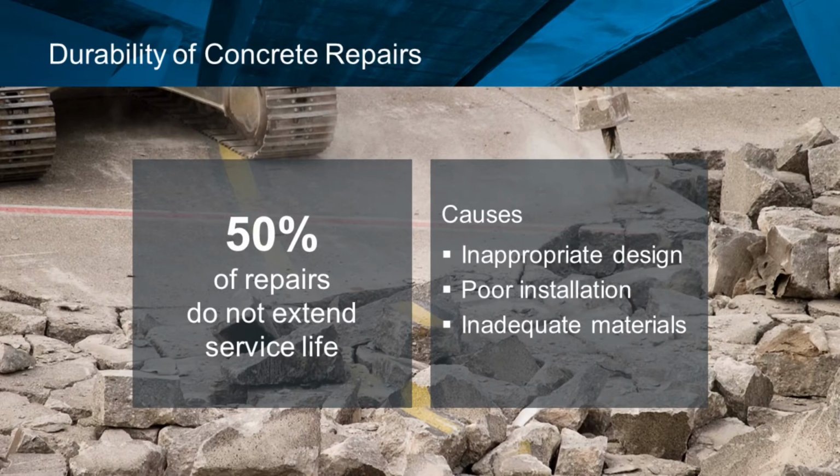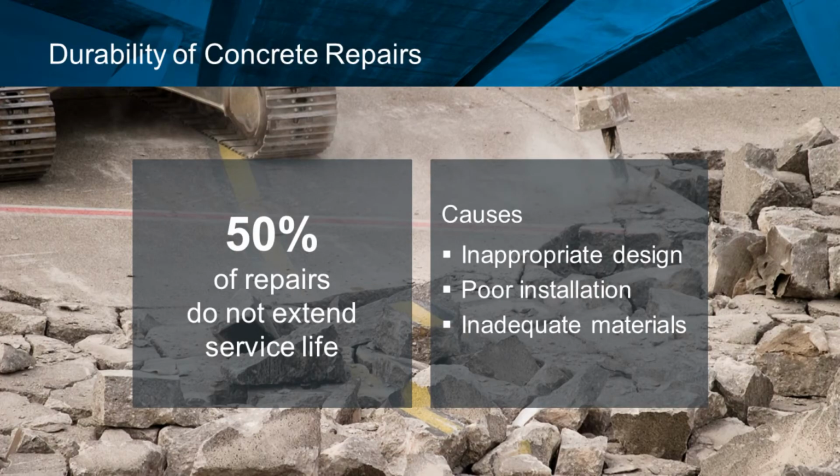Recently there was a survey that's been performed. Well, I say recently, it's about 10 years ago, but the picture was not looking really good in the US and in Europe regarding concrete repairs. The percentage was roughly 50% of success for concrete repairs, and the reason is that, as I was mentioning, constantly doing the same type of repair, regardless of the extent or cause of deterioration, is like flipping a coin.